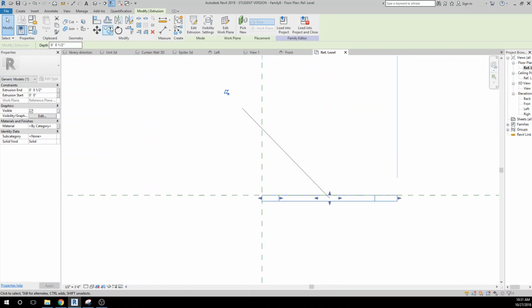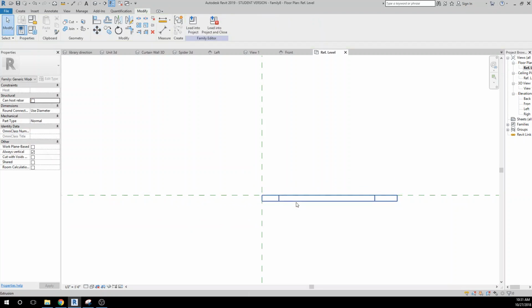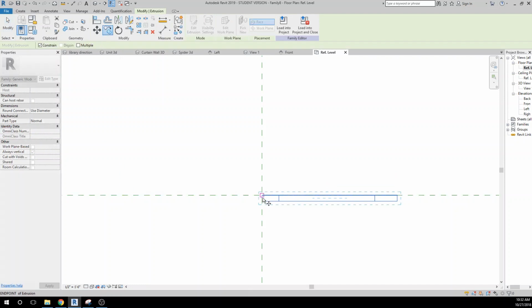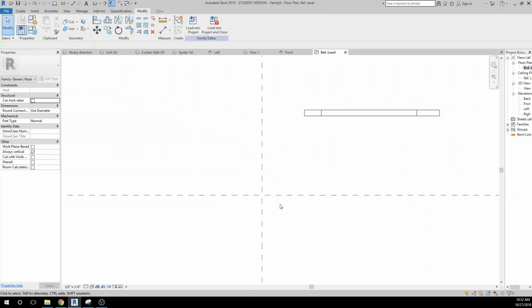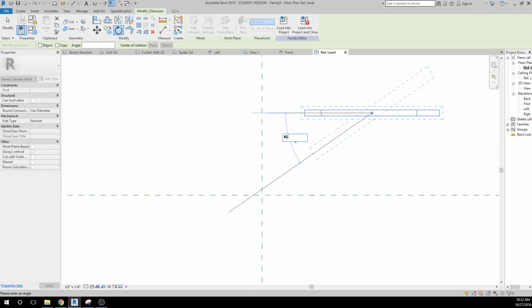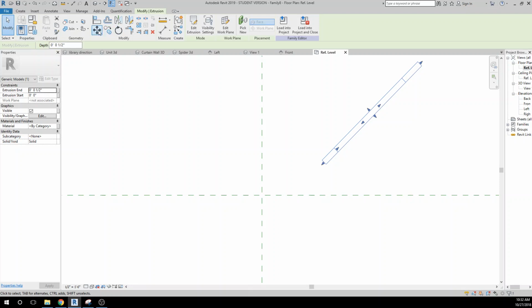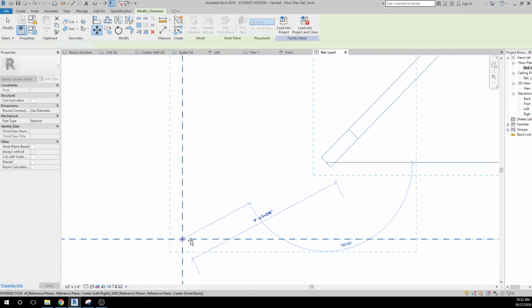We'll zoom in here. I'm not sure this is going to let me offset this. It's probably locked. Let's see if I take the constraint off. Actually, I'll do this another way. I'm going to take this item, unconstrain it, get it copied over here, and delete this. Now I'm just going to take this and rotate it 45 degrees, and move it, if I can grab this center point and move it to the center of here.